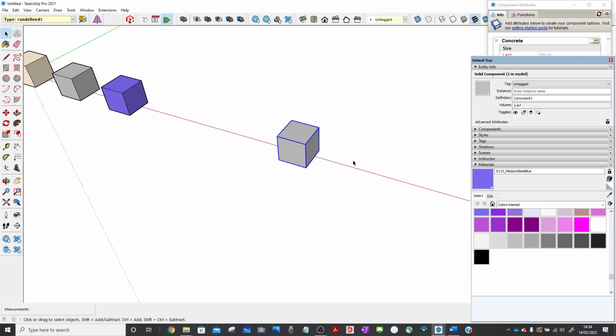And at this point, what shall we make? Shall we make a floor slab? How thick? Now I'm not a concrete specialist, so I believe these are fourth year, yeah? So in your concrete structures, how thick would your concrete floor be normally? 150? Right, that's an absolute minimum, yeah. Near 200, depends. We'll go with that now. So let's call this a floor.